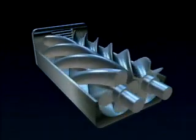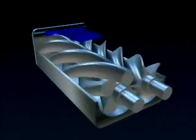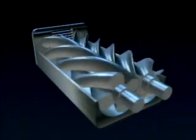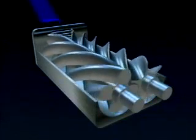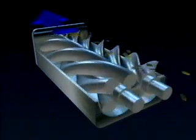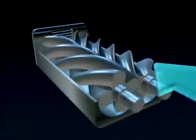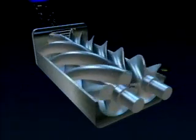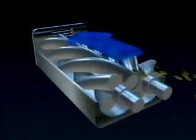Let's look at the basic steps in the compression cycle of an oil-flooded rotary screw compressor. Compression begins as air enters the housing and the rotor shafts begin to rotate. As the lobes and grooves intermesh along the length of the rotors, air volume is reduced and the pressure rises. Oil is injected to absorb much of the heat generated. The mixture of compressed air and oil exits through the discharge port on its way to an oil sump or separator. Finally, a coalescing lubricant and air filter remove most of the remaining oil and return it to the system. The air exits and flows on to the aftercooler.